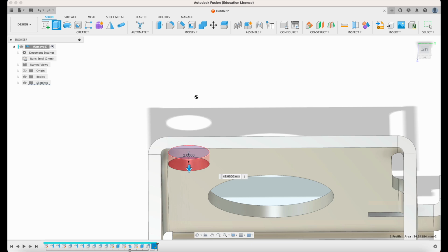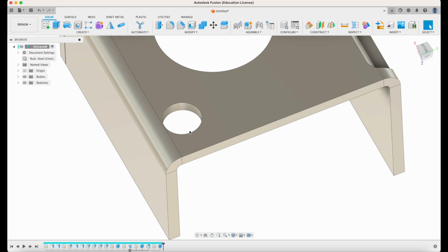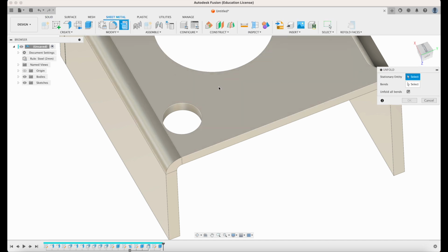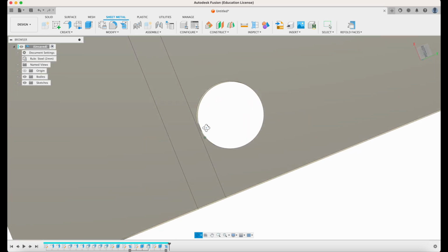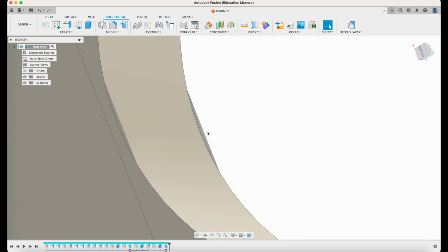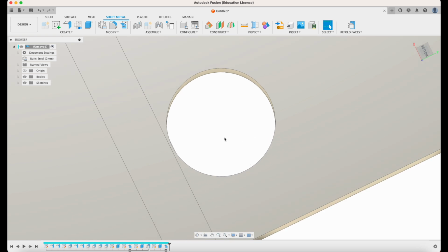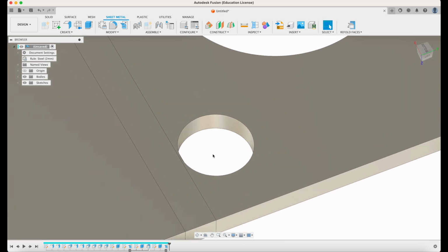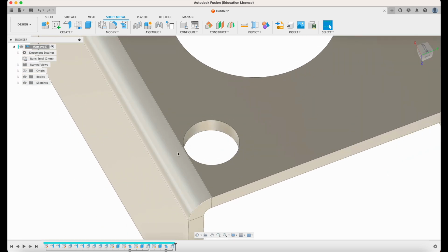Okay, and we cut our hole, so we have our hole, and it's showing a nice hole. It looks perfectly circular. And if we unfold, it doesn't seem to be changing. However, you can see these two weird faces. Okay, now this is the start of a problem, but Fusion is not going to give an error about this. You can refold your face, it seems fine.